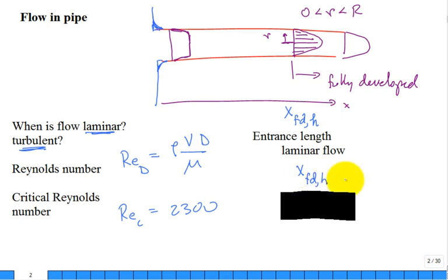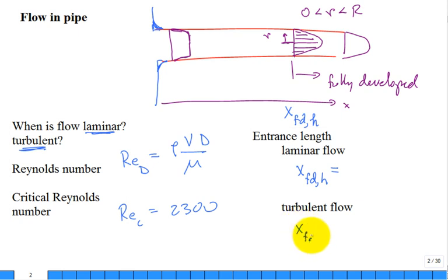Well, it depends if you're anticipating the flow to be laminar or if you're anticipating it to be turbulent. So if it's turbulent, it has a much simpler equation that I would just round off and say it's approximately how many pipe diameters? Do you remember this one? How many pipe diameters? Yep, 10. 10D. 10 pipe diameters.